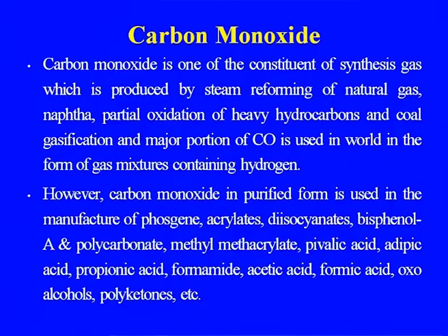Carbon monoxide, as I told you, is one of the constituents of synthesis gas, which is produced by steam reforming of natural gas, naphtha, partial oxidation of heavy hydrocarbons, and coal gasification. A major portion of CO is used in the world in the form of a gas mixture containing hydrogen, and I discussed the various products which we are getting from this CO and H2.